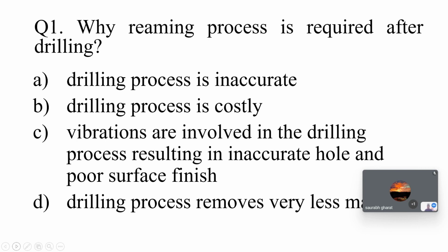Okay, so why is the reaming process required after drilling? "Drilling process is inaccurate" is the wrong answer. "Drilling process is costly" is again wrong. "Vibrations are involved in a drilling process, resulting in inaccurate hole and poor surface finish" is the correct answer. "Drilling process removes very less material" is the wrong answer. So this is the only correct answer.